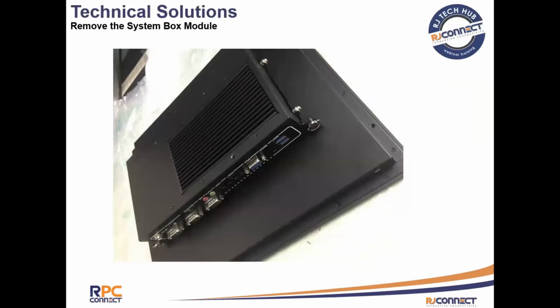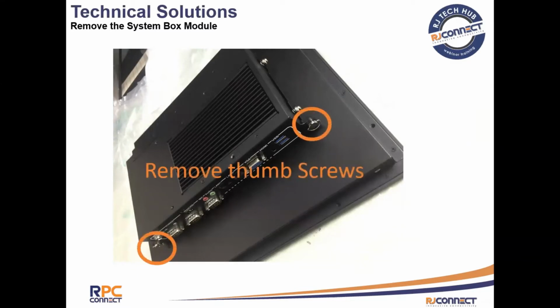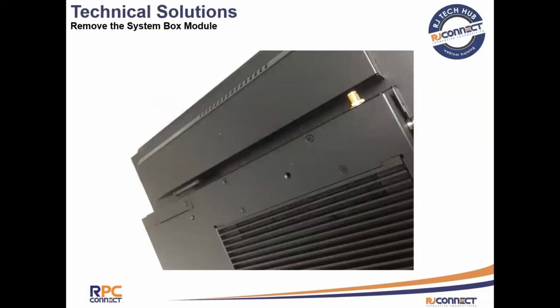And then, as you will see, after you turn it, you need to release 2 thumb screws as indicated on the slides. And also here, guys, you can use a screwdriver to unlock the thumb screws. Once the thumb screws are removed, you can pull the modularized industrial panel PC box module downwards to detach the system box module from the modularized industrial panel PC display module.